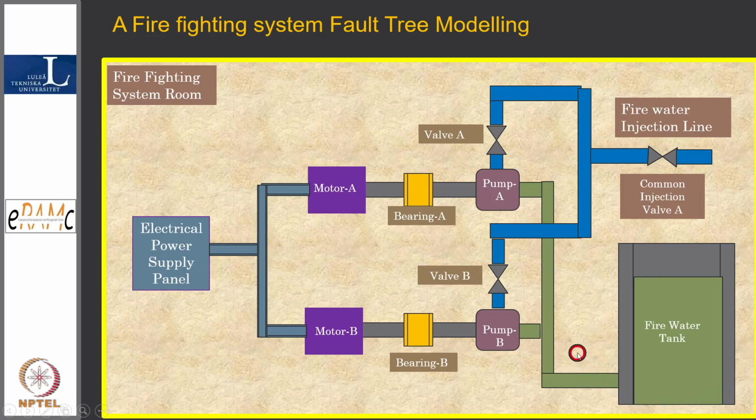But sometimes in the analysis you have to take some decision that structures, passive system, the failure probabilities are very low. So when I do a common cause failure, though in principle it is fitting into the common cause failure thing, I can ignore that, because no leakage, and these tanks are required only when the injection occurs. Otherwise, we see level, and these levels are communicated to the control room. Any drop in this level, 10%, and I have not shown here, the tank will automatically be brought to the normal level. This is the operation. So I can ignore this, but let us see how the fault tree will evolve.